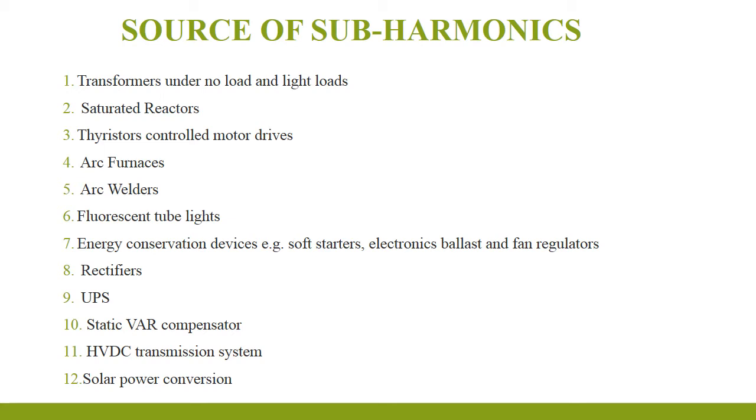Now we will talk about the sources of subharmonics: transformers under no load and light loads, saturated reactors, thyristor controlled motor drives, arc furnaces, arc welders, fluorescent tube lights, energy conservation devices like soft starters, electronic ballasts and fan regulators, rectifiers, UPS, static var compensators, high voltage direct current transmission systems, and solar power conversion can be the sources of subharmonics in any power system.